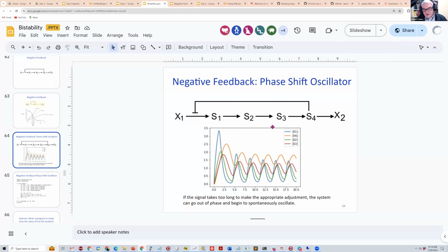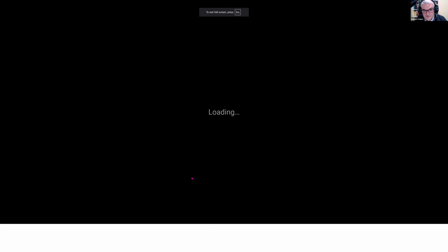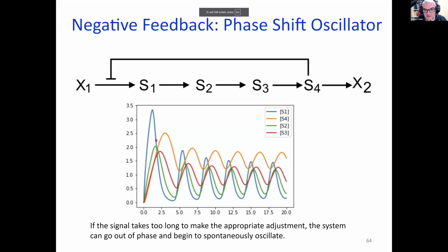It turns out that each species here can contribute 90 degrees. With only two, you can only get up to 180. You can't actually hit it. So you have to have an additional one, which will take you up to a maximum of 270 degrees. And that'll ensure that there's at least one place where you can get exactly 180. And that's the thing that then destabilizes the system.